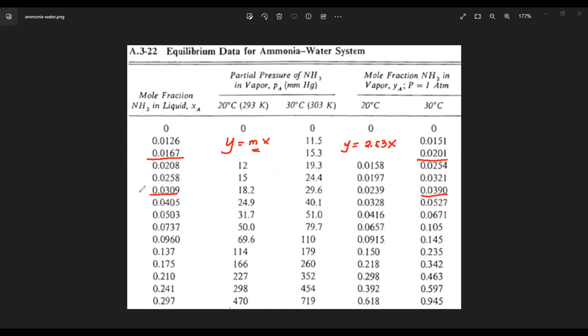But if you're going to ask me if it's the minimum solvent requirement really, and you're to determine the minimum solvent requirement, whether it's gas absorption or stripping that we're talking about, it's always safe to go back to the solid balance in which you're using the inert streams. So what do I mean with the inert streams? The L prime and the V prime equation multiplied to not the mole fractions, but the mole ratios. Okay? From there, you'll be able to get the minimum solvent requirement.